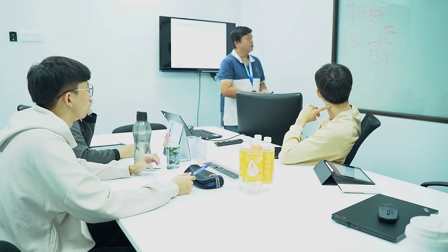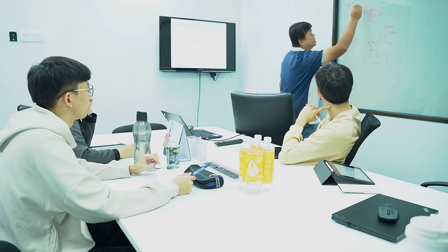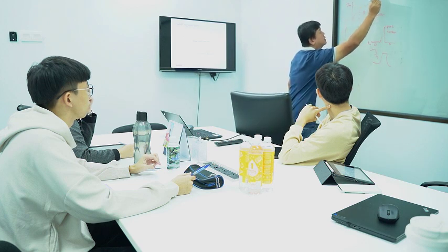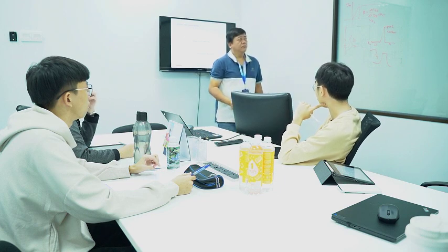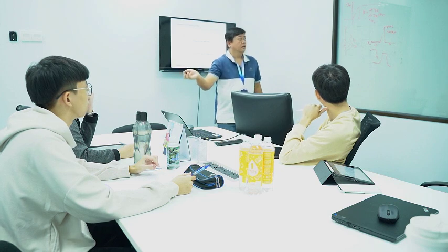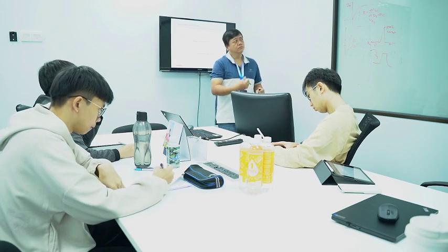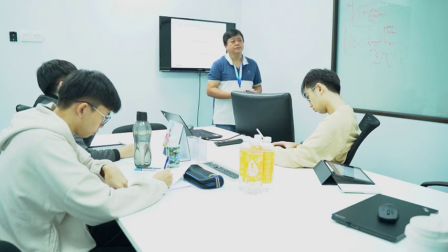This is a must have, right? Ideally it will be exactly flat, but there's some going up. That's why in a real actual MOSFET device, they still have some R. R in saturation will normally be a few hundred kilo ohm to mega ohm, depending on your process. Right, it's very high. So as I mentioned, if you want high gain, you need a high output impedance, right? So you need to bias the transistor in the saturation region. This is a key thing, right?